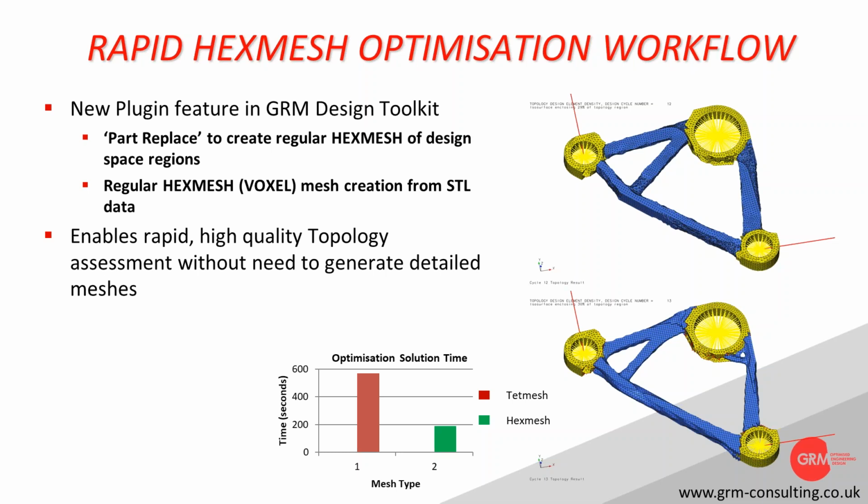The TET element is not really the solve issue, it's the number of grids or nodes that dictates that. But when it comes to the topology optimization and the process of the optimization step, we've greatly simplified the number of design variables from the 120,000, i.e. one per element, down to 20,000 here. Taking just this example, the solution time went down from just shy of 600 seconds to under 200 seconds. So there's a speed up as well as cleanness of the results.